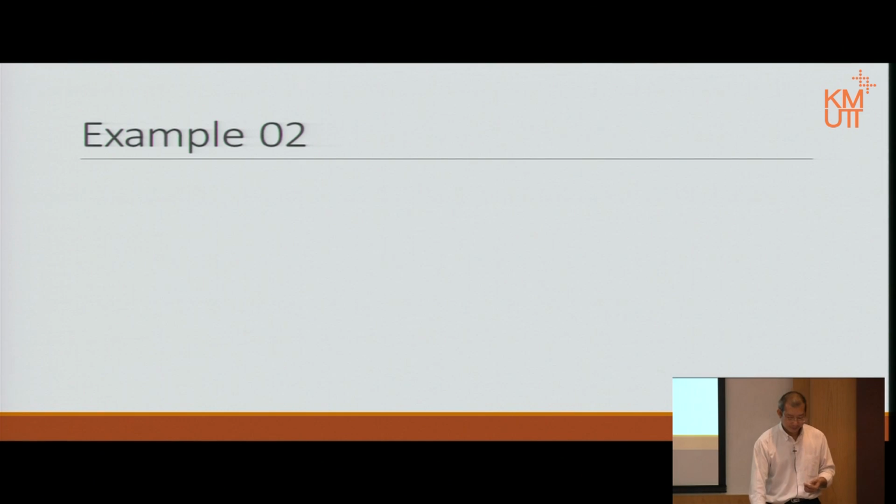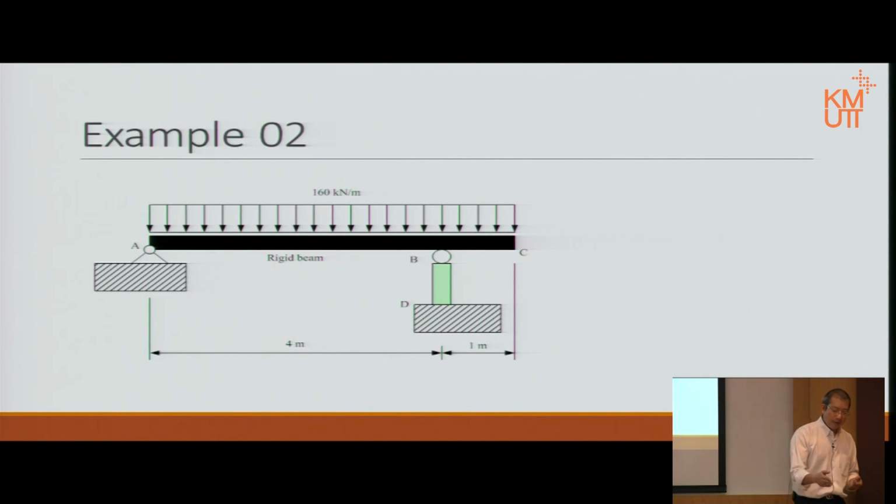Let's look at a picture. There. We answer stress in BD, we answer the movement of point B. What we haven't answered yet is how much point C moved, but there's no column there. How to calculate? Again, the keyword is rigid beam, meaning it doesn't deform. This one here starts off as a straight line. Point A cannot move. Point A is a pin support.